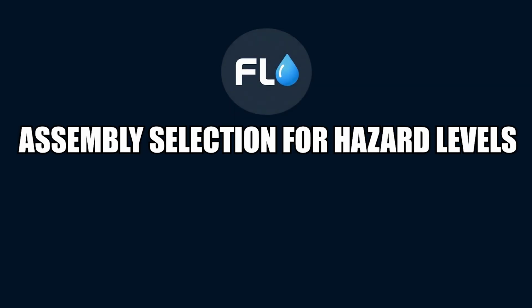When we're talking about the proper assembly, if I have a health hazard, what assemblies can I use? Well, if you have a health hazard, you can use the RPZ, you can use the air gap. And on some of the irrigation, if it doesn't have back pressure, you can use your PVBs and SVBs. It depends. Now, if you're on irrigation and you're going to pump in, you've got an on-site sewer system, or you're going to pump in chemical injection, you're going to use RPZ.